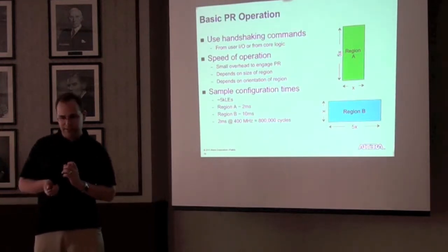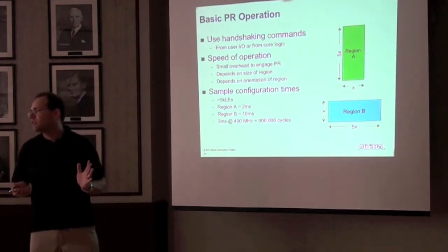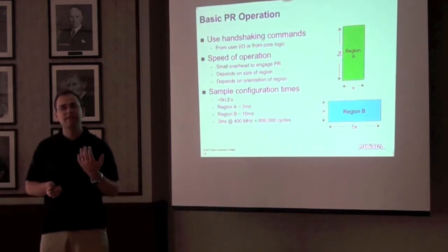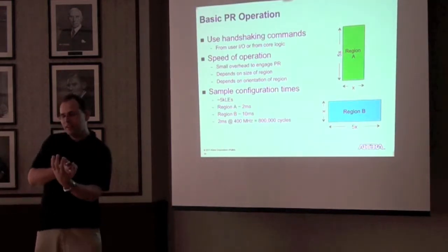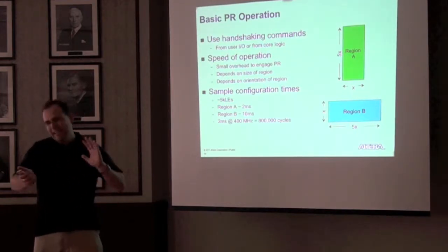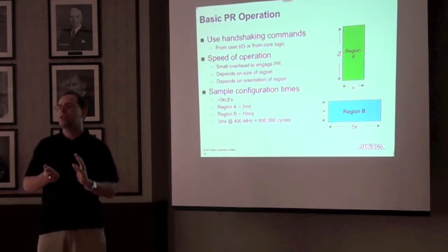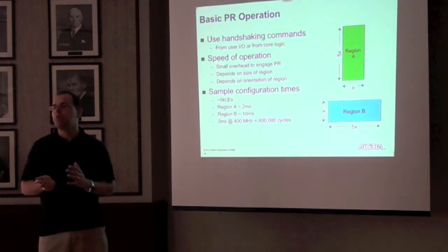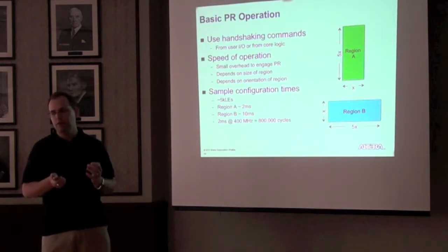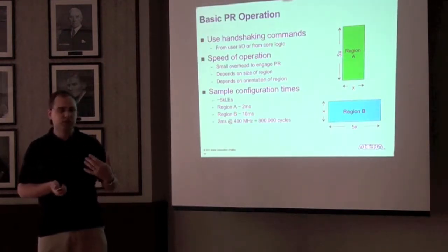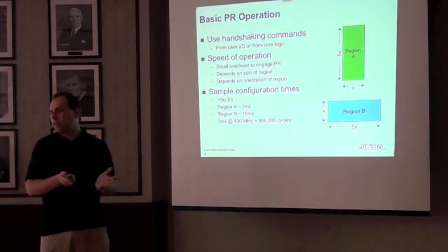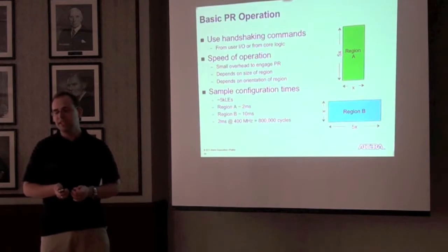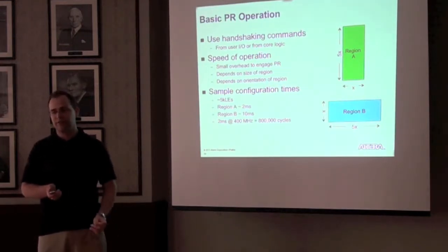Just to put that in perspective, 2 milliseconds, if your circuit is running at 400 megahertz, represents 800,000 clock cycles. So any idea of changing a group of LABs and instantly being able to use that new functionality is just not possible given the speed of configuration, which is a strong function of the hardware support that I described earlier. The way that the hardware is built pretty much dictates how fast we can reconfigure.